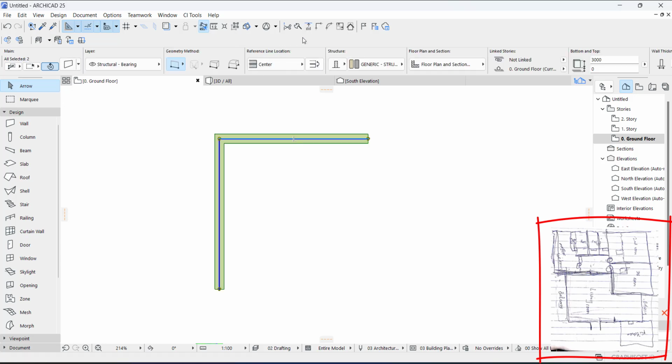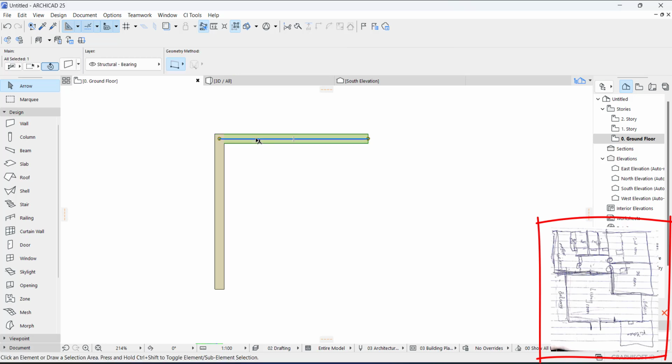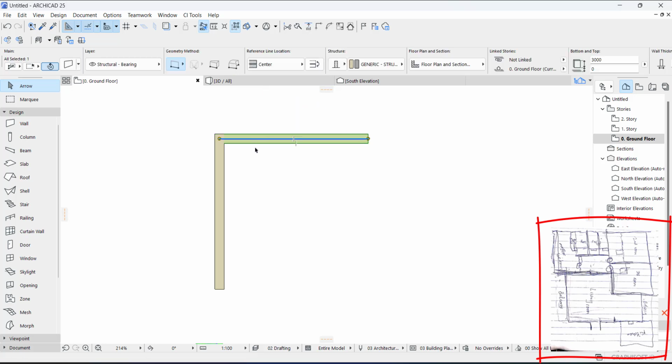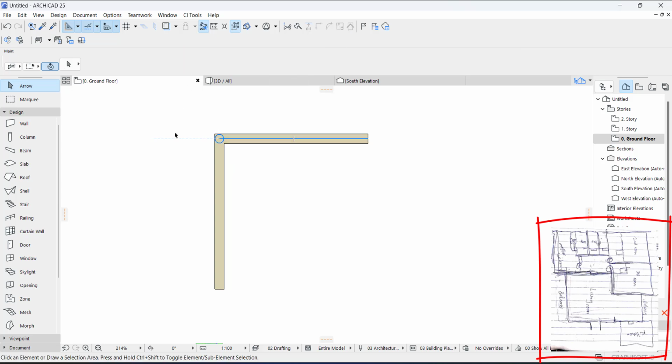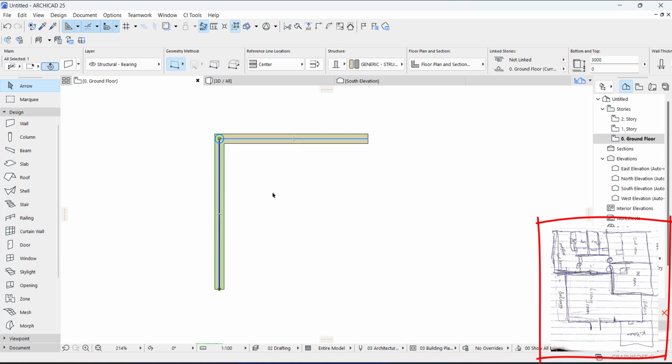You suspend by clicking this, right? Suspend the group, just click this. You see that there. So you can only select one wall when you have suspended the group, because when you draw with a continuous wall, it is grouped by default. So when you want to move each wall, you have to click this now so that you can move each wall.